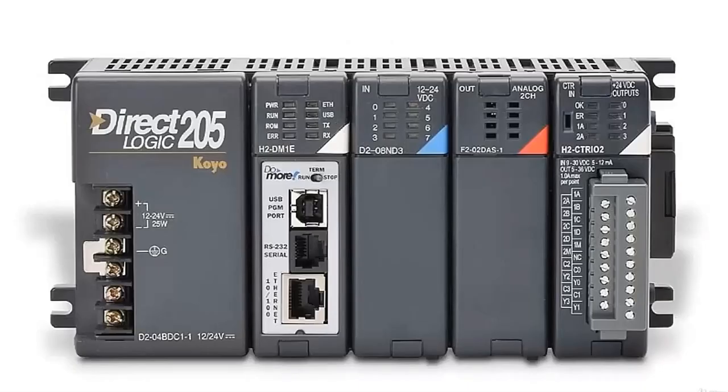But by using modules instead of PLCs having everything all-inclusive, the PLCs are very scalable. If you need a system that only has 20 channels of I/O, you don't have to pay for 300 channels. However, if an existing project needs to add a few devices and you're called out to the retrofit, you don't have to install a brand new PLC. As long as you have room on your DIN rail, you can probably just add 1 or 2 more modules and keep everything exactly the way it is. So all in all, it's a good system.